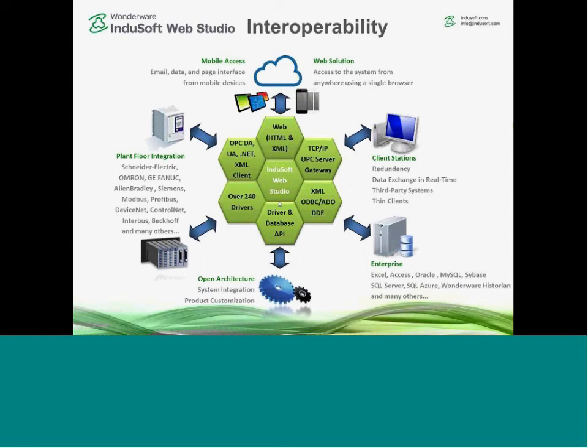The interoperability piece of this is that if you look at this diagram, as InduSoft Web Studio tags are at the core of this, we can basically get information from any device, database, OPC, client, or server architecture, or the internet into InduSoft Web Studio, and then share it with any of these other devices. If you notice, these arrows are bidirectional.